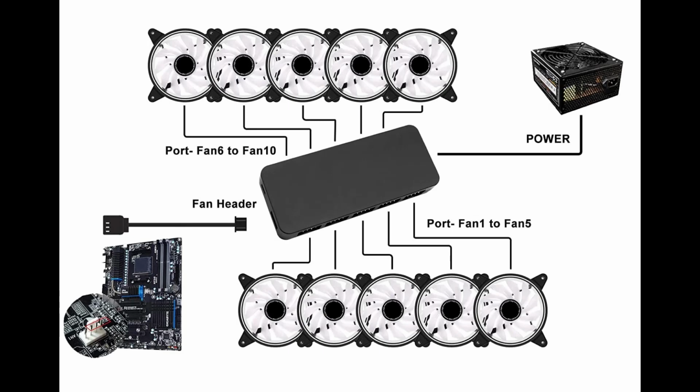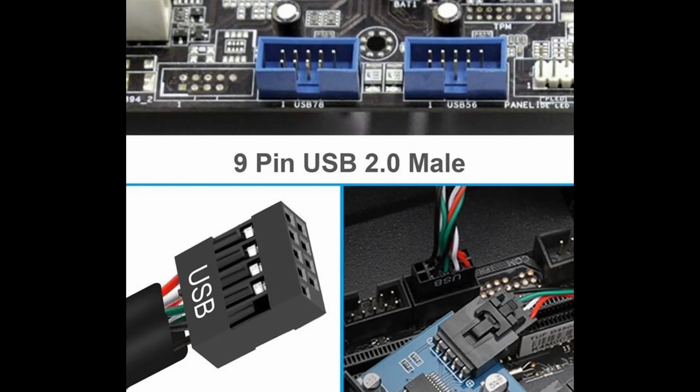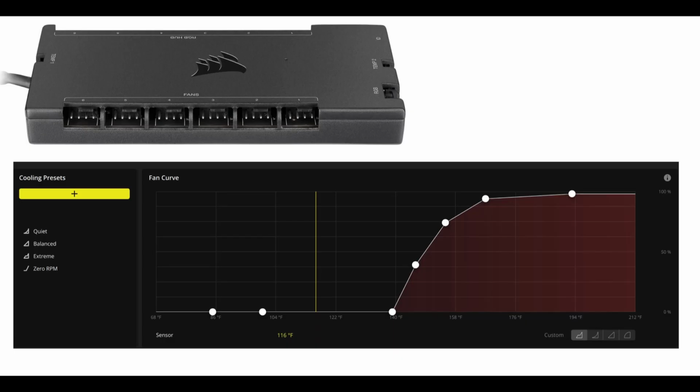Between the motherboard fan connections and a kit you may be able to run 10 fans. Using one fan on one connector, try to avoid using splitters. They draw more current through the motherboard and that is not ideal. The advantage to many of the kits is that they can be added to almost any computer that has a USB 9-pin connector on the motherboard. For example, name brand companies have software support that can help you customize their fan profile. This means that the user can start and stop fans according to temperatures within the computer sensors.